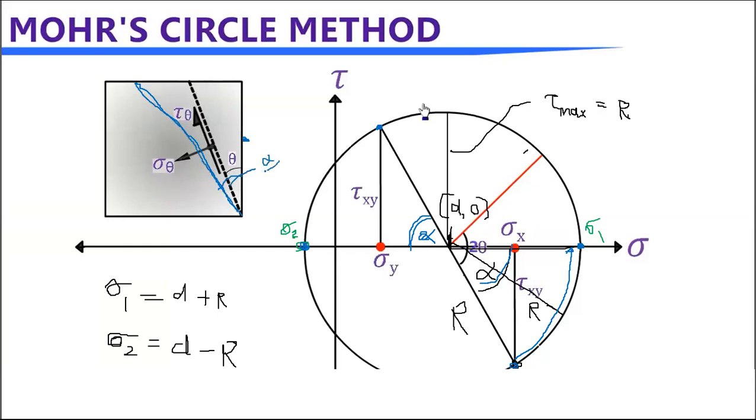real element, right? And there you will find, so it's a compression tension, so you will find a tension, shear stresses are 0. And from this element you will have to go in clockwise direction alpha by 2 to find the minimum principal stress.